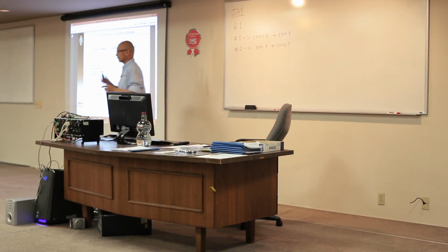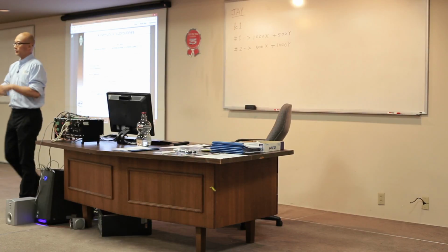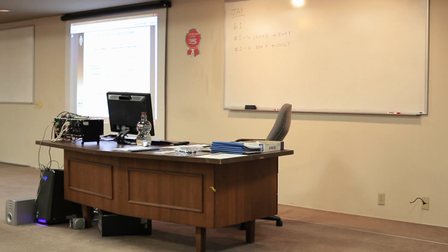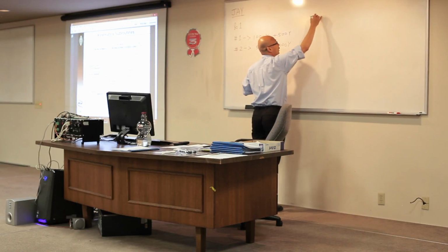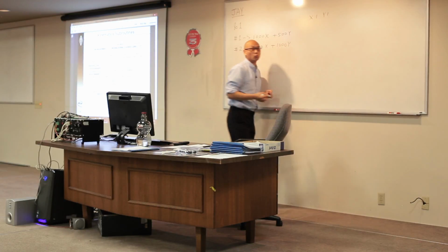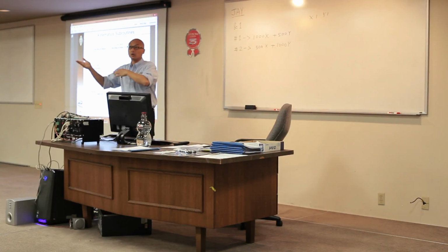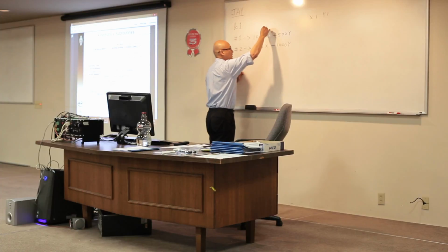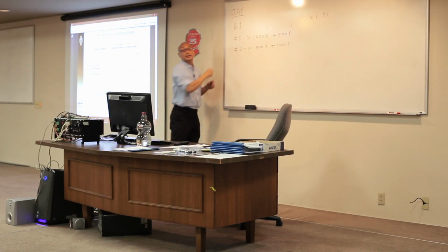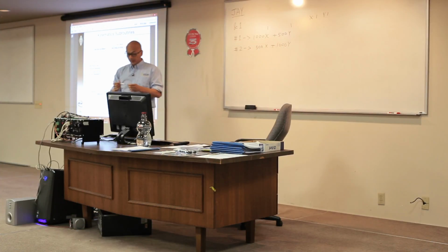The reason for that is, in the beginning of the motion program, when we talk about motion program, you have x something, y something, z something, right? So that means your command is in terms of axis. Meaning, if you say in the motion program x1, y1, you want the axis to go to x1 and y1. That means this is 1, and then we calculate the motor position for you, right?